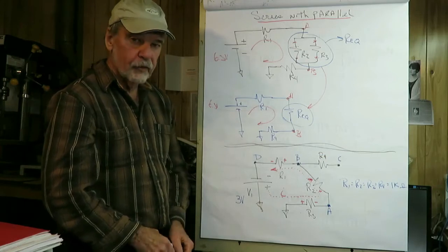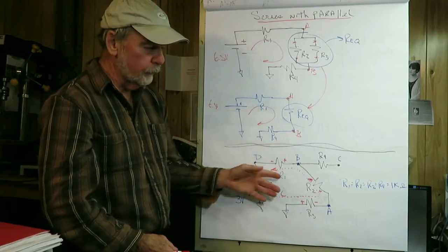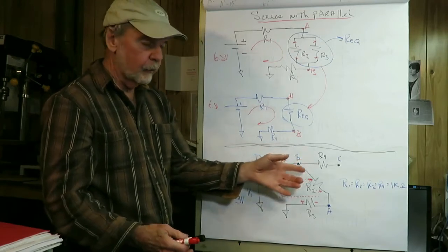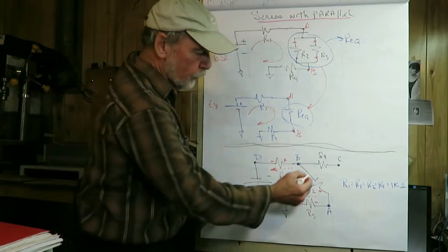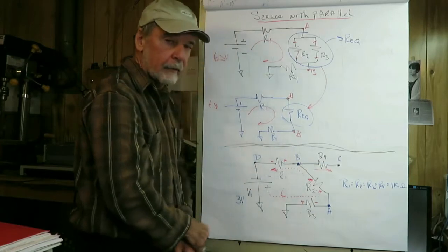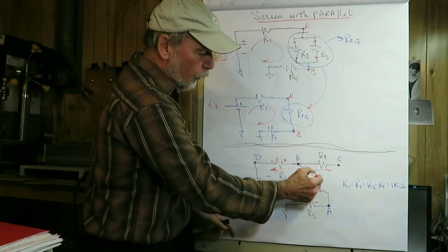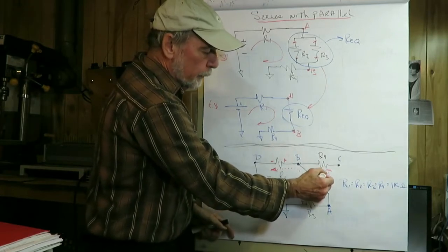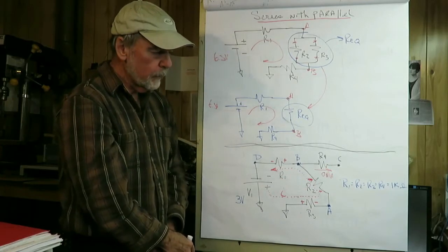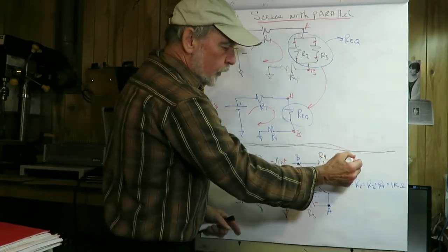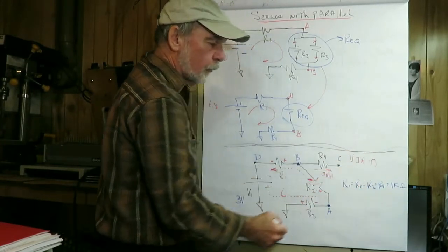Now you see dangling resistors occasionally, and you see them in problems, because in the real world you don't want to do that because you waste a part. Not only that, you waste printed circuit real estate. But the way to handle this is to note this. It's an incomplete path. There's nowhere for the current to flow when it gets here. So the current flow through this is going to be 0 milliamperes. So what's the voltage drop across R4? Well, V is equal to I times R, and since I is 0, the answer is 0 volts.